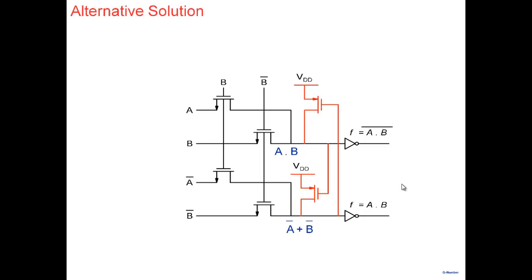So you're not adding a PMOS at every gate. It's not a transmission gate. You don't add a PMOS here, you don't add a PMOS here, don't add it here. It's only at the output that you add it at this particular point here. So it's still much more efficient than the earlier transmission gate-based pass transistor logic. You add only a PMOS here and a PMOS here.